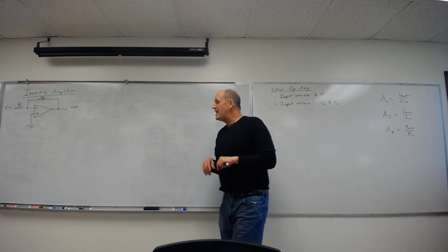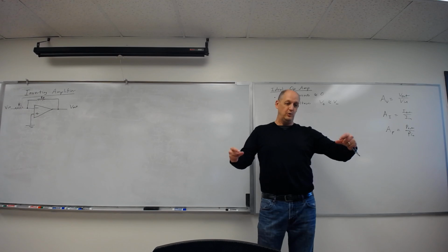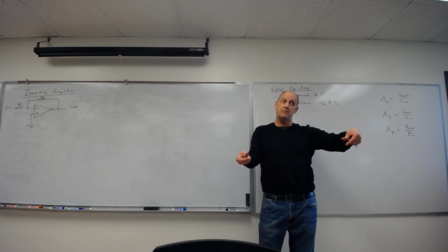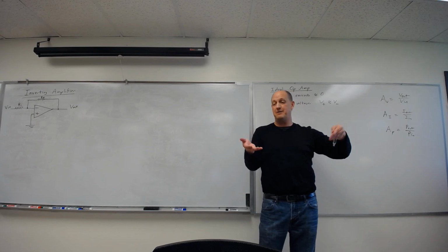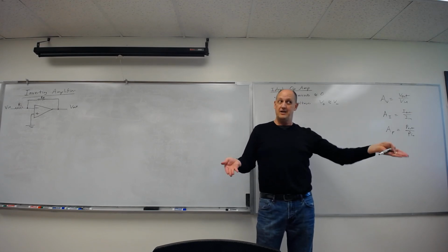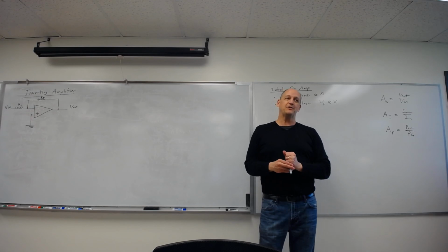That also has an advantage in that op amps are fairly inexpensive, so if I buy a whole bunch of them and I get two of them that have the same number I'm going to put in there, but they have individual gains, in reality maybe not quite as exaggerated as we have, one might be 100,000, the other at 115,000, I can plug them both in the same circuit and they'll work the same.